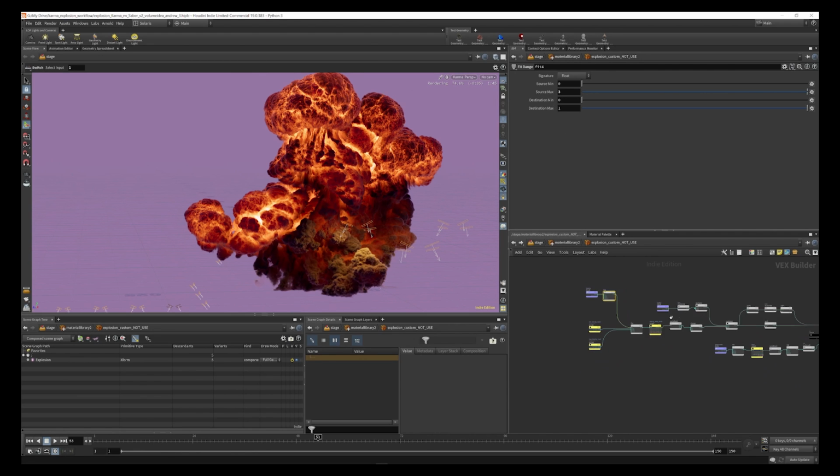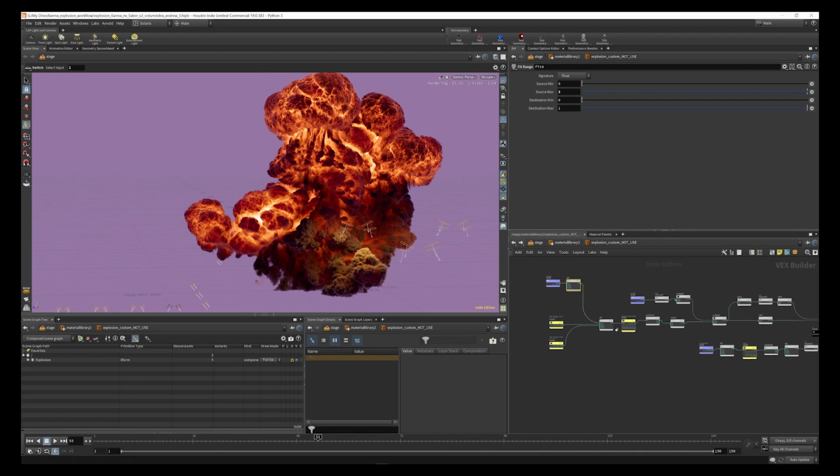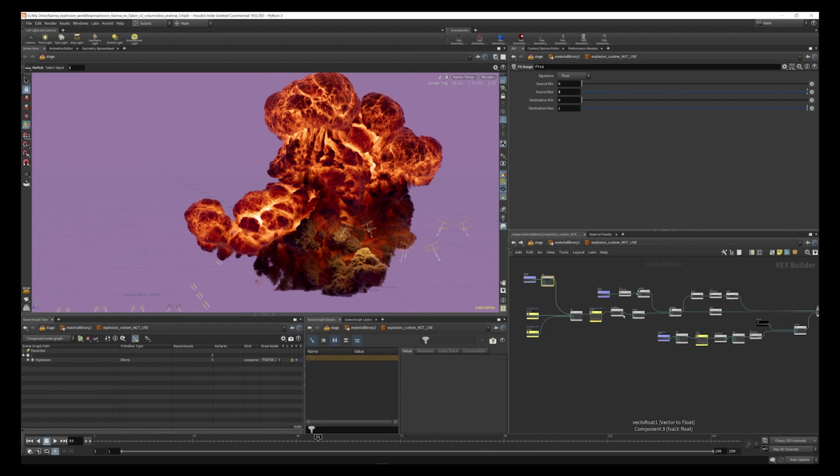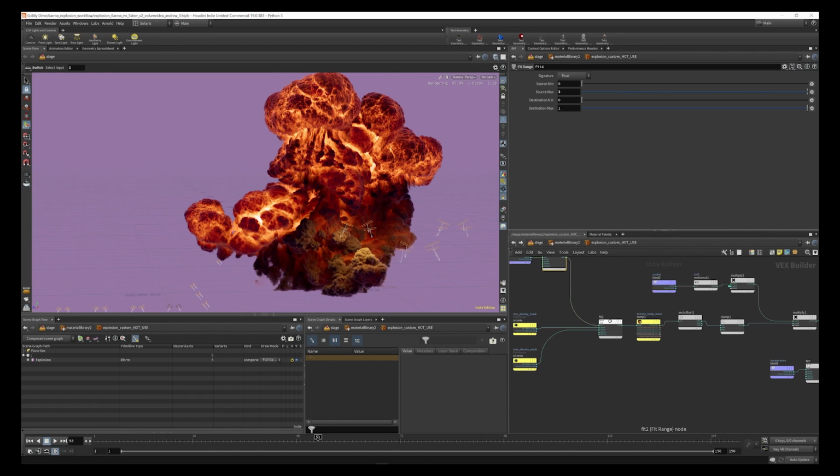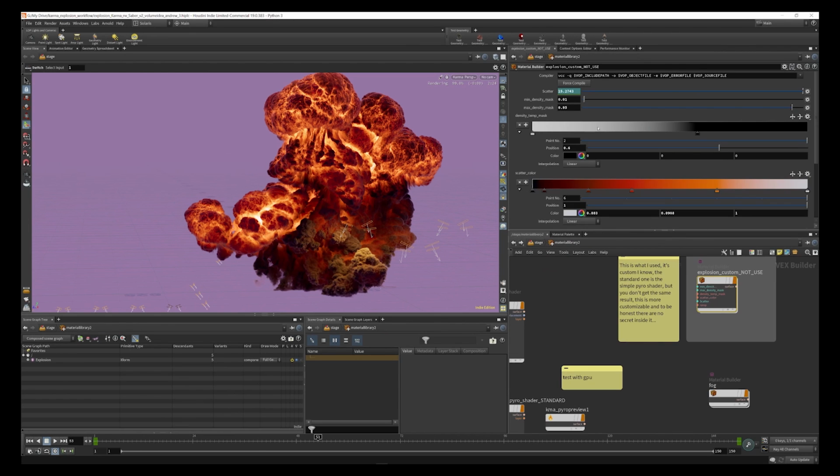So we're going to put down this fit, and what we're doing here is the inverted shader trick. What that is, is that we're basically computing the density from the shell towards the very center. So the center part is obviously going to have a higher density than the very edge. And what we want to do is invert those values. So we're taking the density and fitting it with a fit range, and using the min and max, we're inverting this density value with these values that you see here, and that way we can isolate the shell.